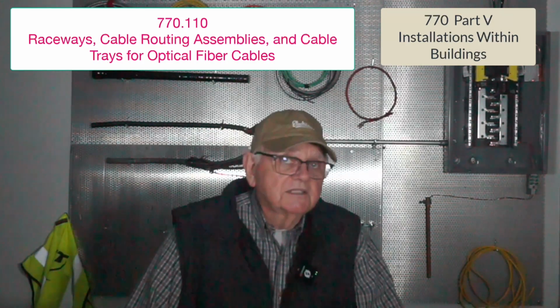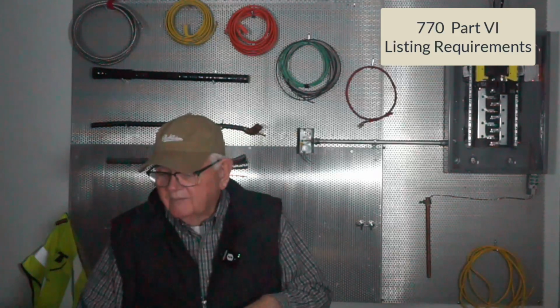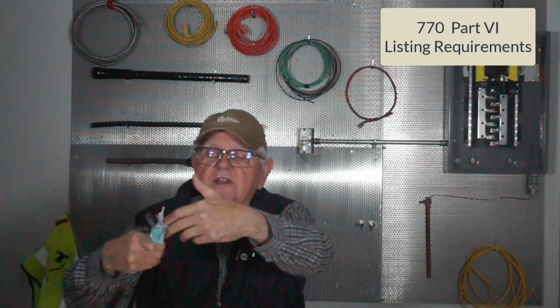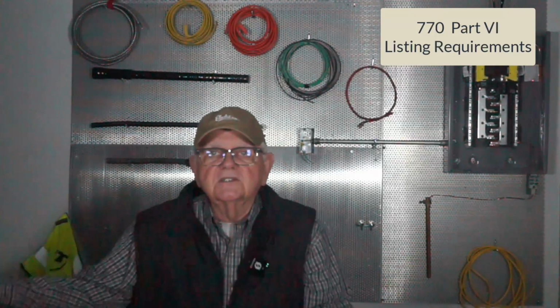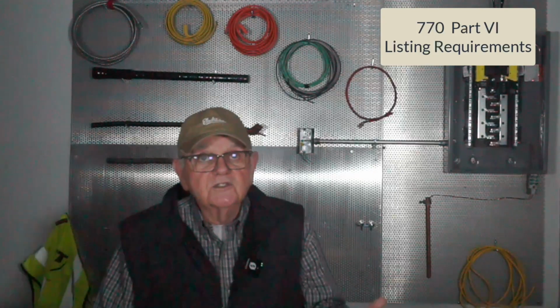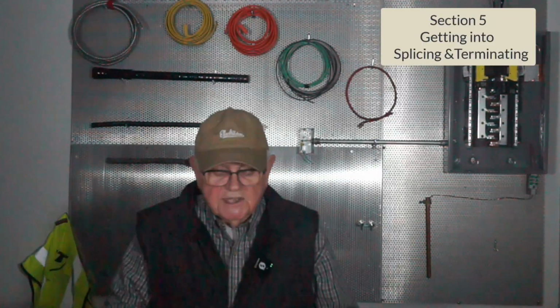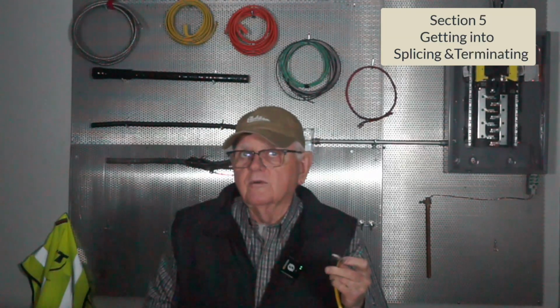Part 6 is my listing requirements. It's all got to be listed. And also, even that wedge I described that we would use for bonding, that would slip underneath the corrugated metal sheath in this example, must be listed as well. So we're going to use listed components for the installation of our fiber optic systems, and of course the cable is all listed as well. So that moves us into Section 5, which is terminating and splicing of this fiber optic cable.